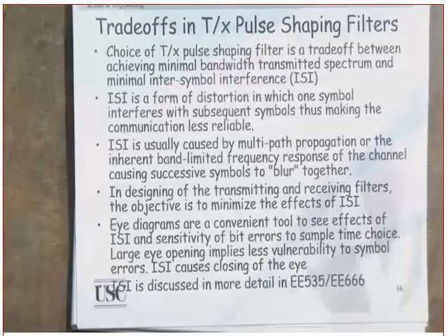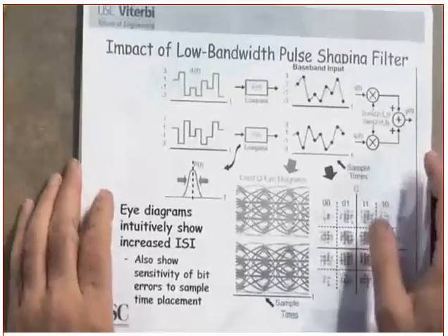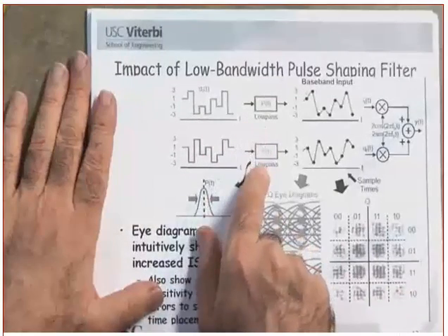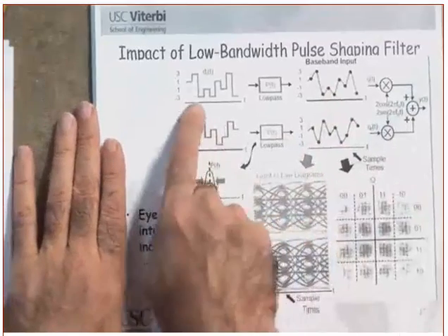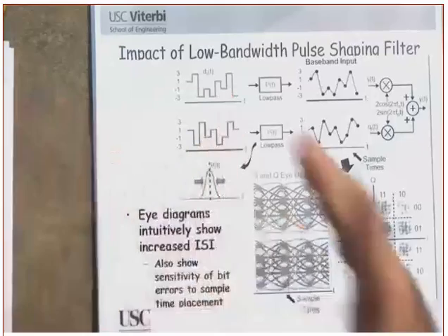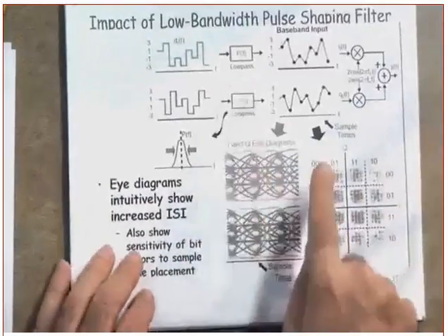The best way, of course, is the eye diagram, because you can see very clearly whether the eye closes. Once the eye closes, that's an indication that the interference is heavy. Let's look at the diagram so that you can see what I'm talking about. What did we do here? We applied this to a low-pass filter, and this is before the modulation. Look at the IQ. By the way, if you look at the IQ here, you will see it wide open. Wide open means the eyes and the Qs are wide open. You can see them. But with the low-pass filter here, look what happened.